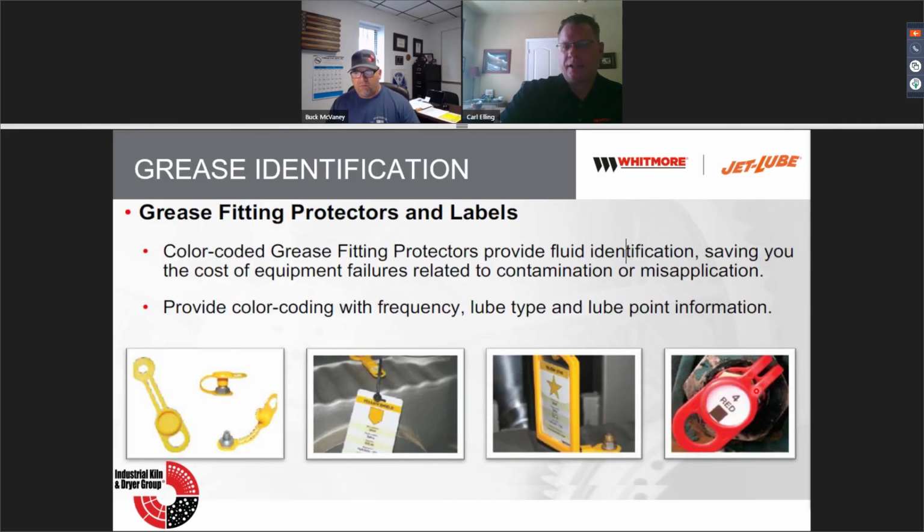Well, let me go back to this one. If you've got a really big unit with several grease points, this number system could go 1 through whatever. So if you decide to take a break or lunchtime comes around and you got up to point number 9 and there's 21 points, when you come back from lunch, you start at point 10 and then go all the way up to 21. So it could be just a numbering system on that asset. Just another idea to share with you guys.